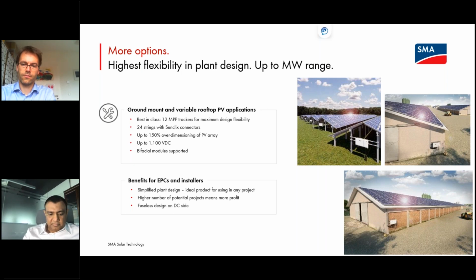especially when you go to the Middle Eastern region, a very good detail, because as you know, the voltage drop in that area, because of the higher temperature of the arrays themselves, is relatively high. So the difference between the start in the morning and the full power of the sun during daytime is very high, I mean the temperature difference. That means the more modules you can put into series, the easier it makes it to get a good yield out of your system.